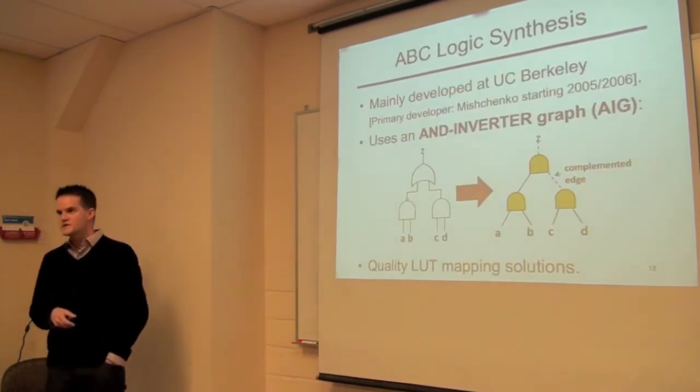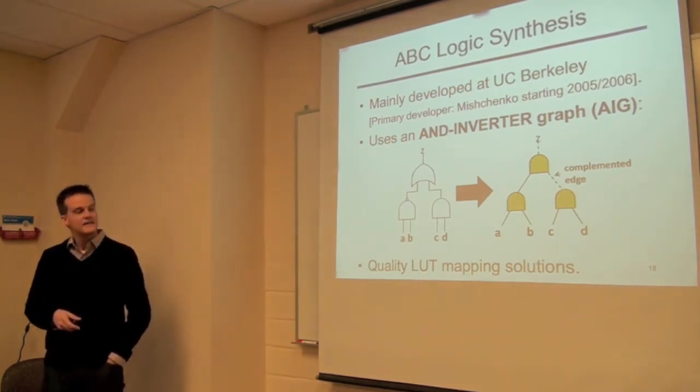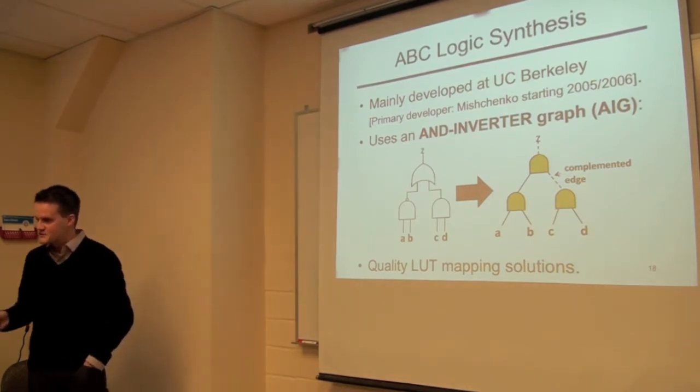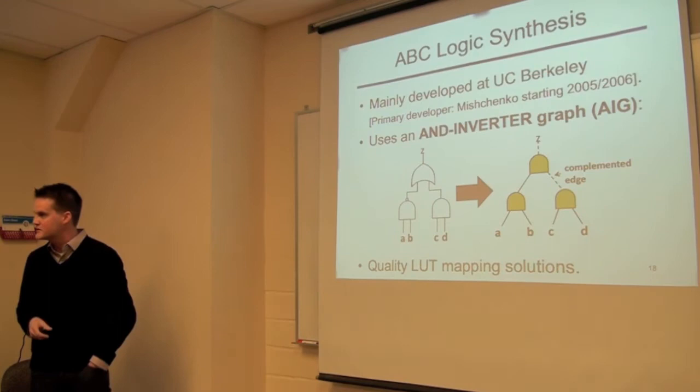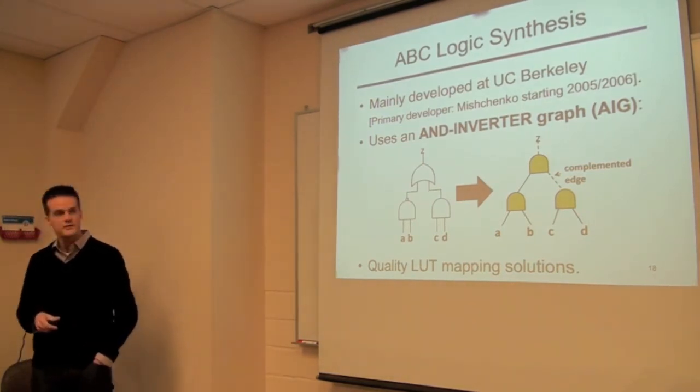Turns out it's actually very easy to map into these. Although the architectures look maybe complicated, it's actually quite easy to map into them with ABC. And in fact, there's been a lot of work previously on trying to combine LUTs with muxes, but historically it's hard to do a broad exploration because it's kind of hard to map into them. But if you have ABC, it turns out it's very easy to find the gating inputs and trimming inputs.